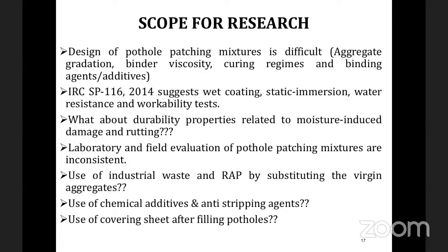Next, the IRC, Indian Roads Congress, has suggested a design and guidelines for pothole patching mixture, that is SP116. The IRC suggests some basic tests like wet coating, static immersion, water resistance, and workability. But it has not focused on durability properties, maybe those related to moisture damage and rutting. Fatigue is not necessary, but we should focus on moisture and rutting. Moisture is due to water, and rutting is due to the wheel load.